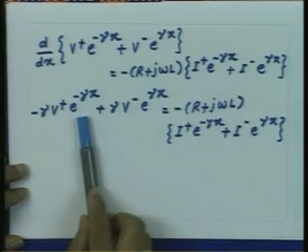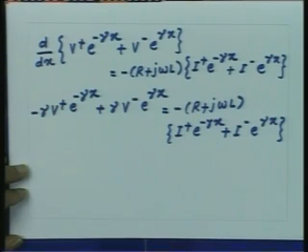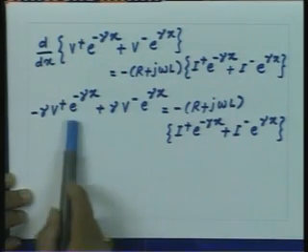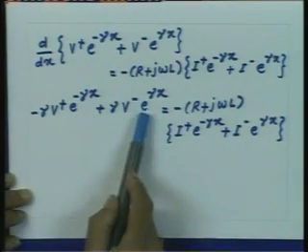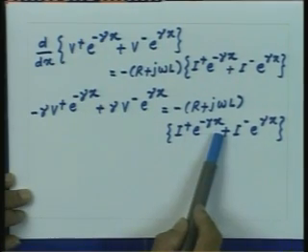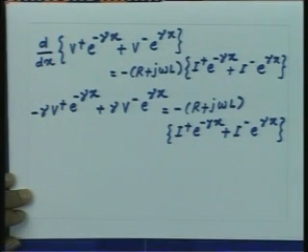This general relation between the voltage and current has to be satisfied at every location on the transmission line. Since the two waves travelling in opposite directions have different phase histories, you cannot satisfy this equation for every value of x unless these individual waves satisfy the conditions at every point on the transmission line.